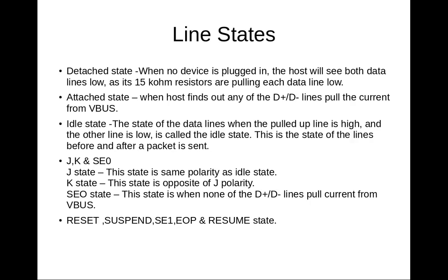End of packet means that the packet that has been sent from host to device or device to host is finished, there are no more packets to be processed, so it sends the EOP signal. So EOP state helps us determine the packet size, when the packet has ended and when it is to be processed. And resume state, as I told you, after suspend state, it has to go to the resume state if the device or host has something for the other.